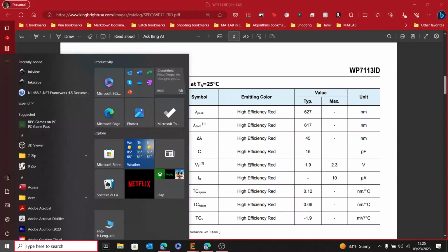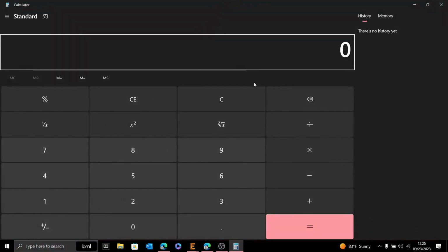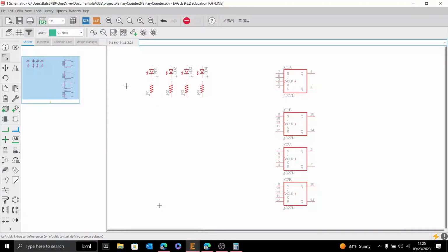So I also know that for our power supply, we are eventually going to use 5 volts. So we'll bust out a fancy little Windows calculator here. 5 minus 2.1, that's 2.9, and then we're going to divide by 10. This is the hard part, remembering your zeros. I think that's 10 milliamps. Looks right. Yes. So we want about 290 ohms. I think I used 300 just for a little extra. It's not an exact science, it just gets us a ballpark. And so that's what we'll do.